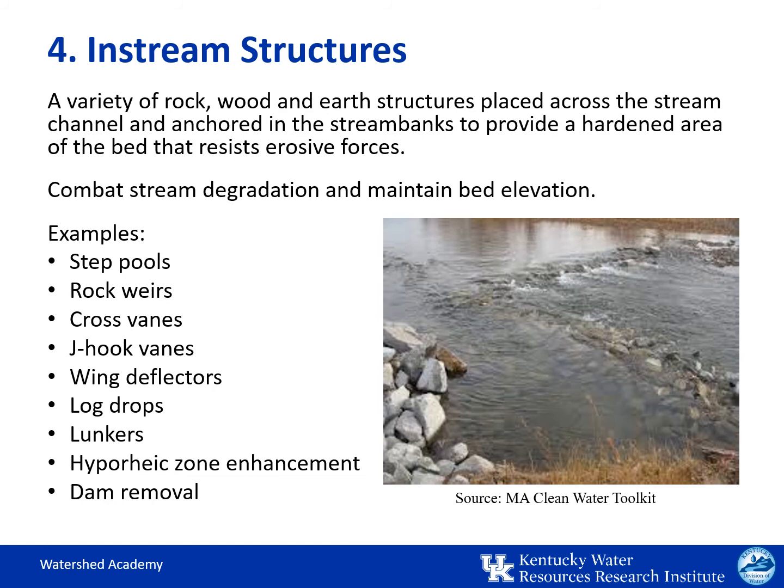in the channel slope. Usually we see in side channels from bed erosion, that is degradation, but a raised bed, aggradation, can also result with no pool or riffle sequences and a shallow or wide channel or with a silty bed. If a stable channel is required for habitat design, then grade control structures should be considered as the very first step in the design process.